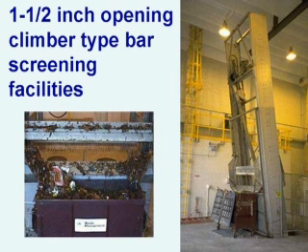The photograph on the lower right is the inflatable dam that I mentioned a little while ago. It is the fail-safe device. It's not somebody stuck up in the pipe as it looks from the back end, but it is actually a rubber dam that's held with compressed air at about 4 psi, and if the upstream level, upstream of the screen, starts to get near the ground level, that inflatable dam will deflate. It goes completely flat on both sides, and excess flow would go through that system.